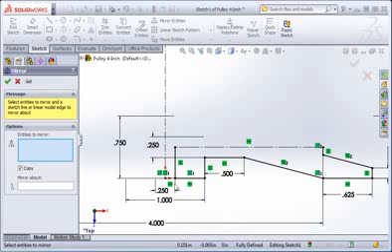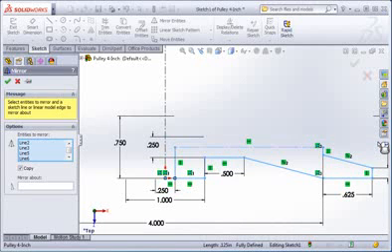So drag the window so that it crosses over this line, and drag it to the right so that it looks about like this. When you release your left mouse button, the lines are added to the list in the Property Manager. If all went well, these are the lines that should be in your list. If you've redrawn the lines, different numbers will appear because every time you draw a line, a new line number is assigned to it. Line 13 should be the construction line.